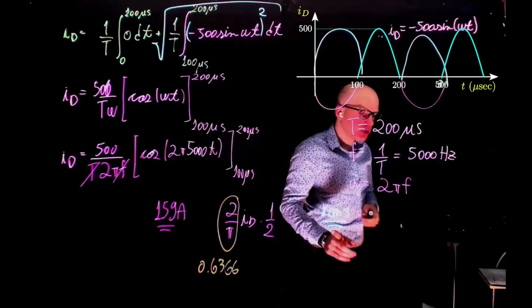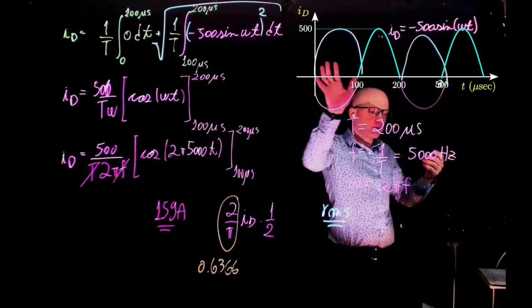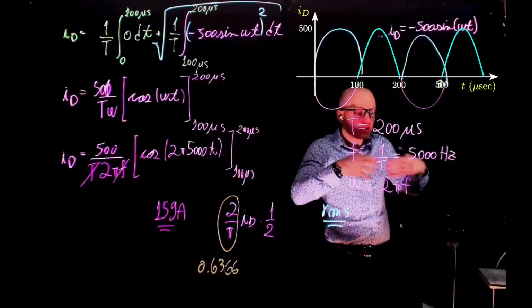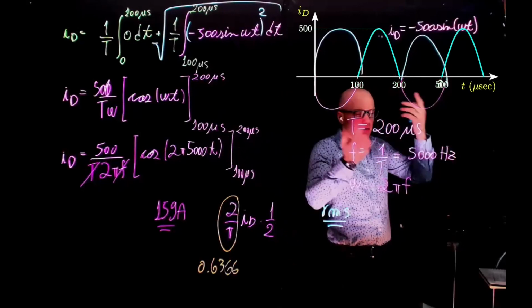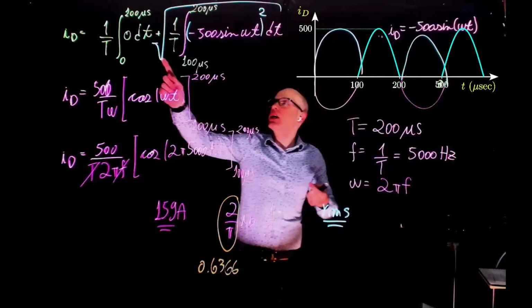Root mean squared voltage. Because indeed, if you take the average of a sinusoidal waveform, it's 0, but it is still delivering power. It happens to be in both sides. Hence the square, which will make everything positive, and then the square root to get rid of the square.